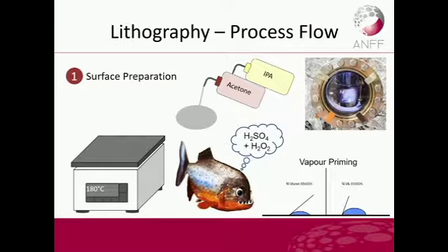First, to do lithography, we need to clean the surface. There are many ways to clean the surface. You can use solvent cleaning, or more aggressively, you can use a piranha cleaning. A piranha solution consists of sulfuric acid and hydrogen peroxide. It's very high temperature. It's actually pretty dangerous, but it will remove all the organics and metals on the surface. Alternatively, you can carry out a plasma process, which uses oxygen plasma. And Caillou will cover that later.